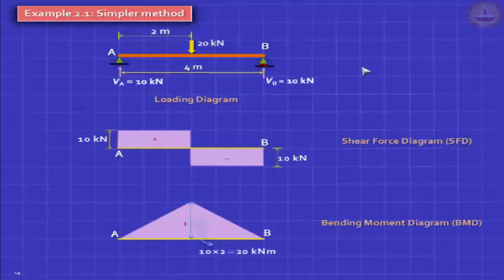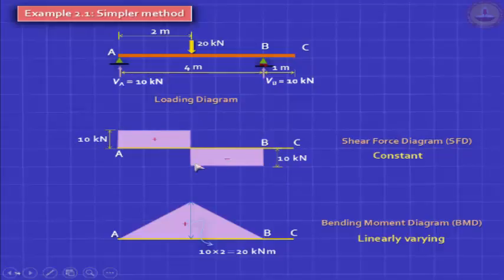That's what you do, in fact. After some time, in the beginning you do the other way. The fast way to do it is to draw the deflected shape. Now bring in this fellow and add it, so that you find there's some lesson to learn from here. The shear force is constant in one half and the other half, numerically the same value, but it's switching sign. And the bending moment is varying linearly. So there is a message to learn from this.